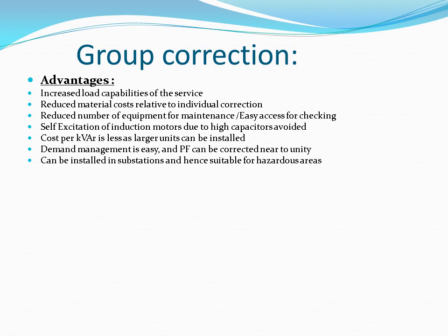Cost per kVAR is less than larger units. Demand management is easy, and power factor can be corrected near to unity. These can be installed in substations and hence are suitable for hazardous areas.